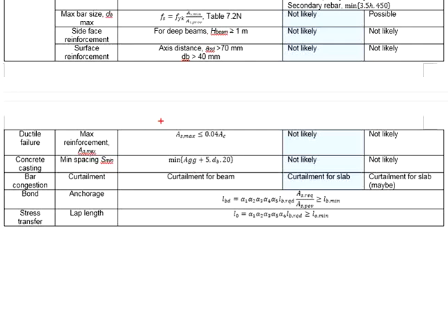In the case that the maximum reinforcement is exceeded, you will need to redesign the beam section. Probably enlarge the beam and increase the effective depth. This can reduce the amount of reinforcement bar required. At the same time, increase the cross-sectional area of the beam so that the amount of reinforcement bar will not be more than 4% of the cross-sectional area of the beam.